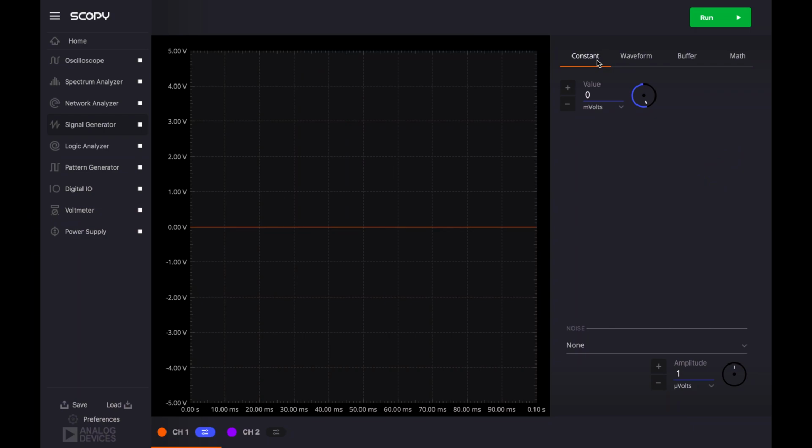So anything past a milliamp is going to actually make this thing chug along, and we'll have labs that actually show you that. And again, that's one of the benefits between a USB device versus an actual signal generator: a signal generator will be able to provide more oomph to your waveform, more power to it. But I digress. So you can use this to generate a constant waveform if you want, a DC voltage.